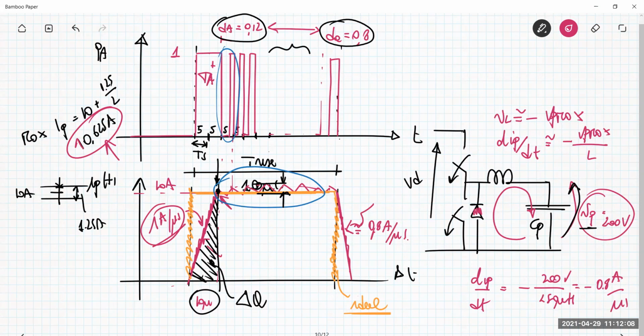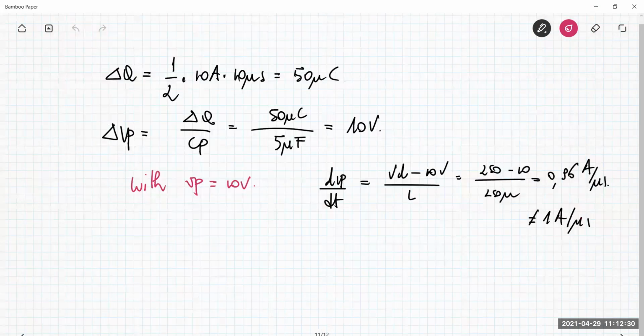In this computation I use exactly 250 microhenry, but with a current rating larger than 10.625 amp. We have to ensure that the inductor does not go into the saturation region of the core during nominal operation, otherwise the inductance goes to lower values, and this is not good. Problems, questions, whatever.